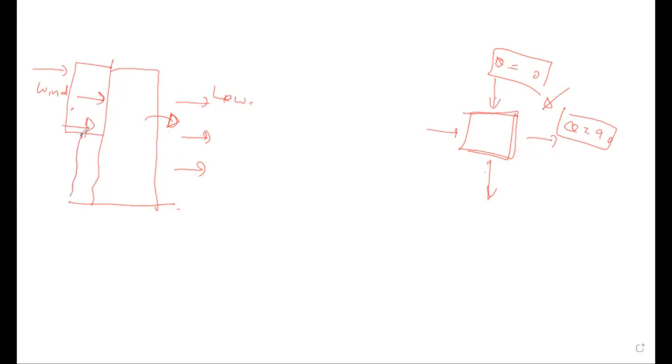In the windward side, I can apply it as a point load, around 70. And for these lower floors, I can apply around 50 kilonewtons. It's not a line load, it's a point load. I'll show the reason. And in the leeward side, the entire distribution is uniform and you can apply around 44 kilonewtons. I will apply the same loading in the y direction also, y direction windward and y direction leeward.